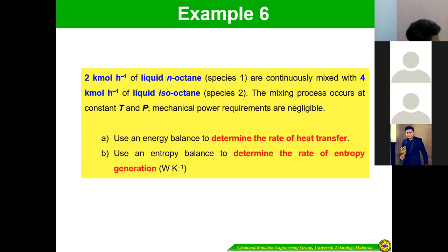So in our reaction now we use water, and the boiling point is 100. Water enters the reactor at 200 and exits at, for example, 50 degrees C, as a liquid. So the water from 200 has to go to 100 first, because there is no change in phase there. Then 100 to 100, the change in phase from vapor to liquid. Then only the change in temperature to 50. Yes, that's correct. Understand? That's why you need the hypothetical path.